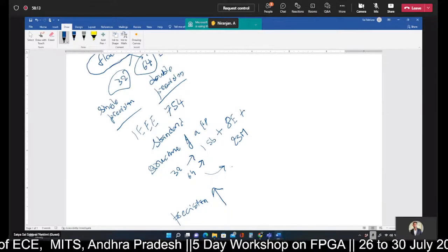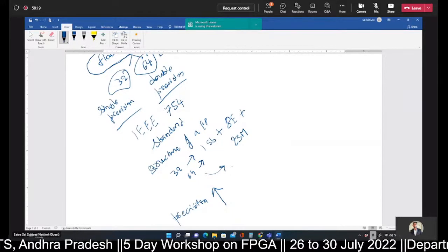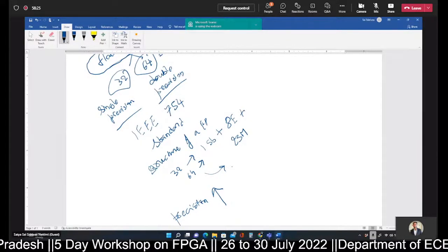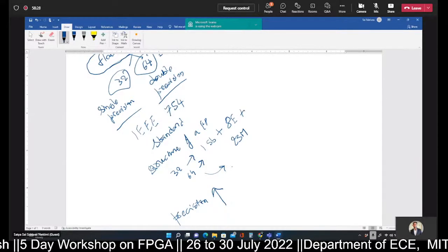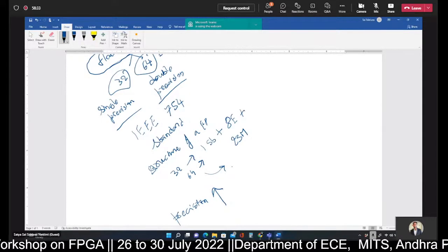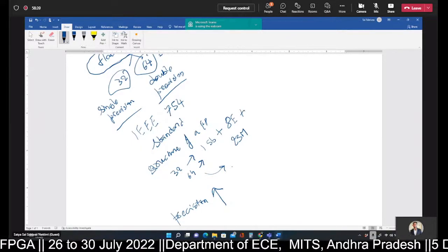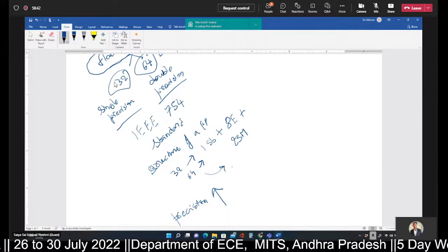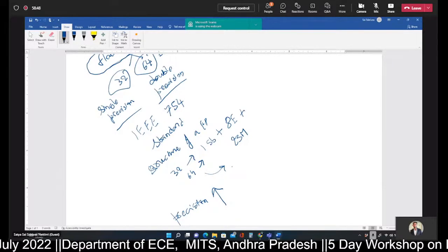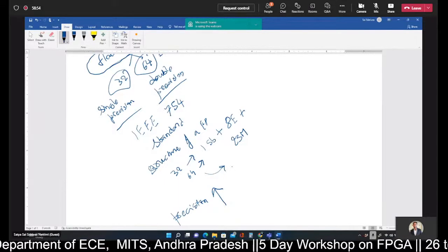With exponent and mantissa, you need to do some operation on the exponent and mantissa along with the sign bit to get the exact value being represented. So if you take all these factors, the corresponding hardware architecture will be pretty complex and huge. Even if you implement it on an FPGA, it will utilize more resources. And if you put it on silicon, in an IC fabrication, the components will occupy a pretty large area. So there is often a trade-off.